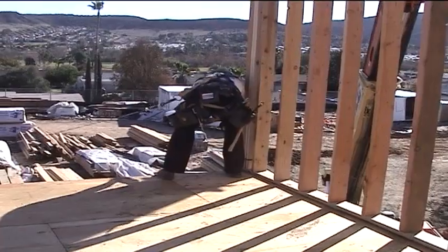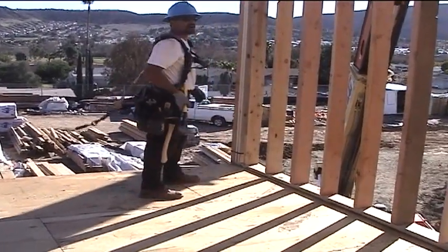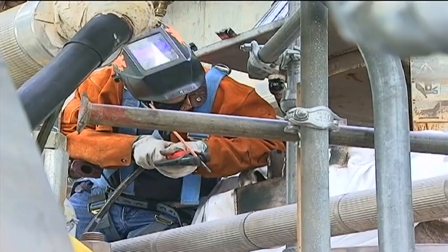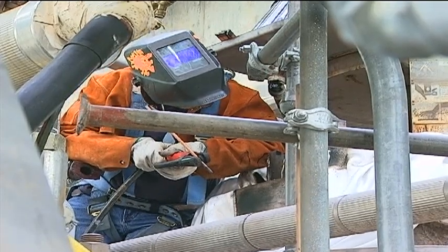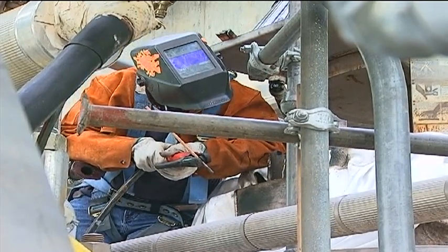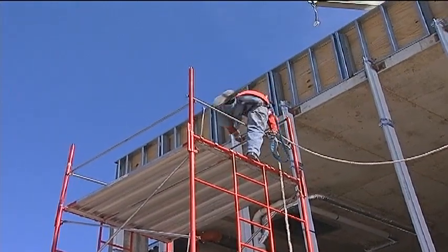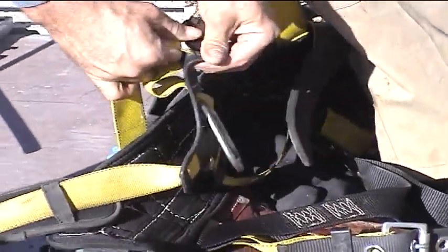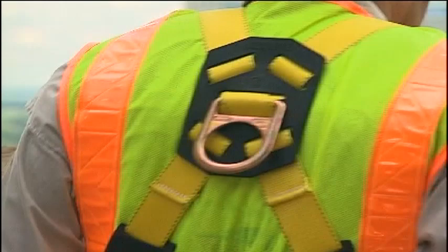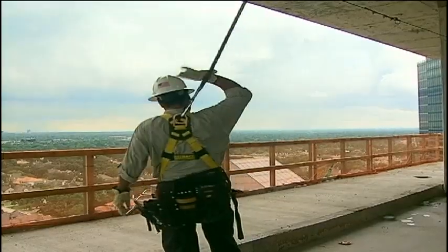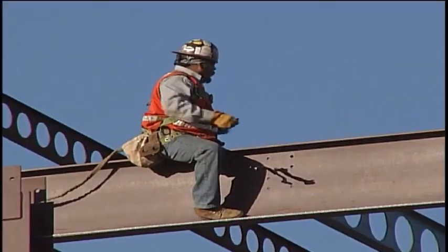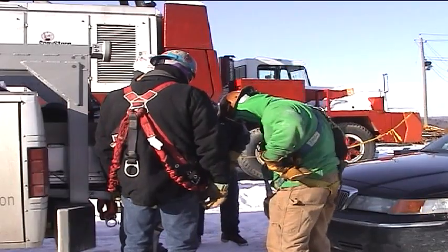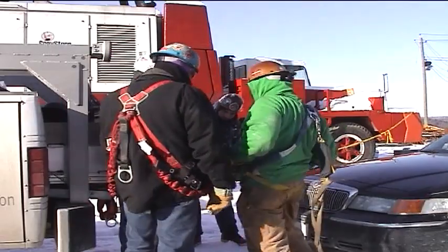Falls are a major safety issue, and using the right protection is necessary to ensure your safety. Fall protection must be used when working on any surfaces more than 4 feet above a lower level in general industry and 6 feet in the construction industry. Remember the ABCs of personal fall protection systems: anchorage, body harness, and connectors, and how to use all the components properly. Know the total fall distance when using PFASs. And always take your training seriously. It could save your life.